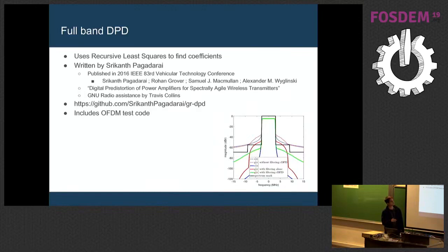Yeah, so I think this blue dotted line here is the original signal put through the power amplifier. We see it's going above his spectral mask. He tries filtering it, that doesn't do it, and so then he ends up digitally predistorting it and filtering it and gets it below the mask here. And so that's quite a considerable improvement, over 25 dB worth of signal to noise ratio improvement.